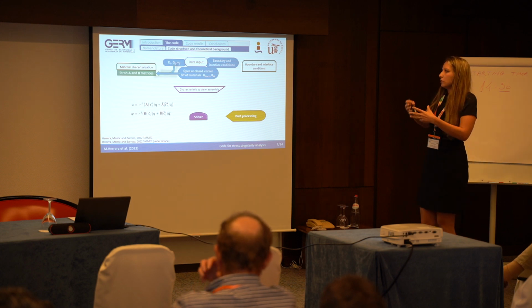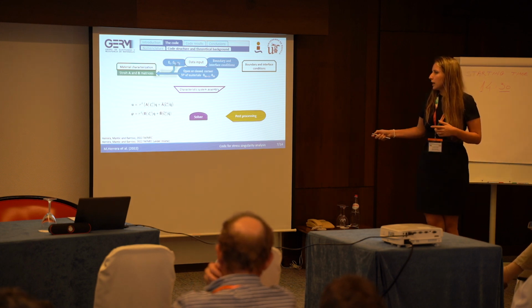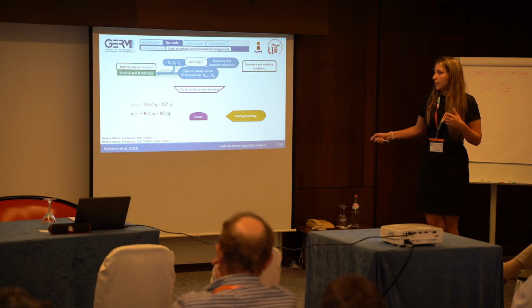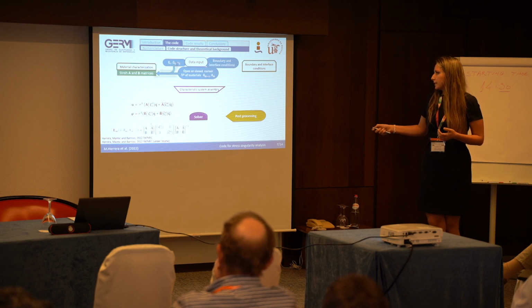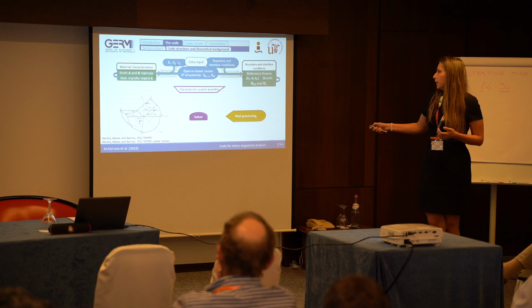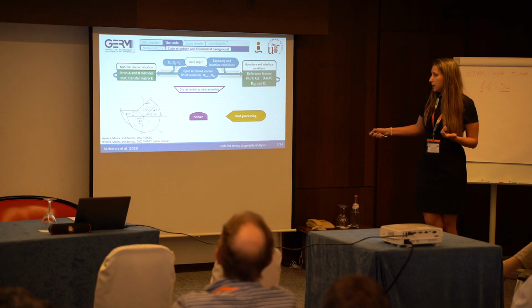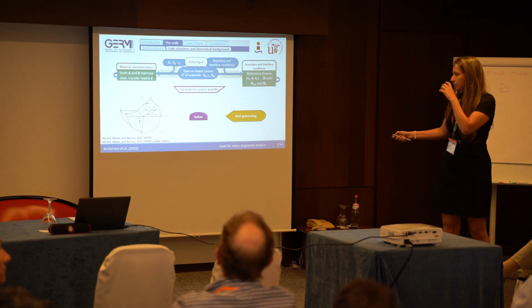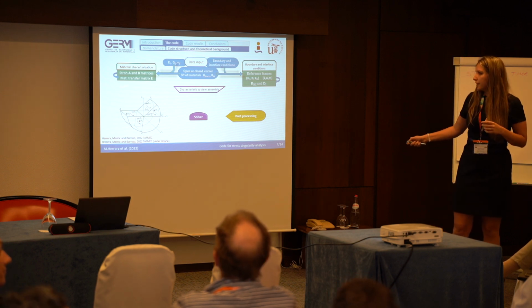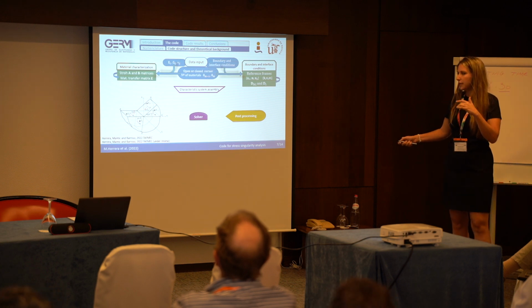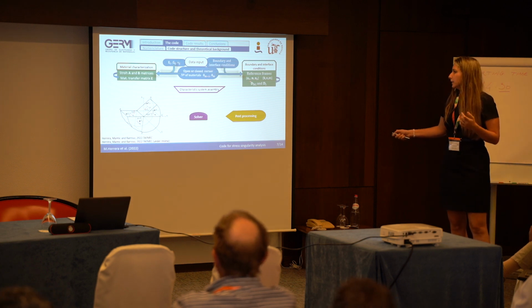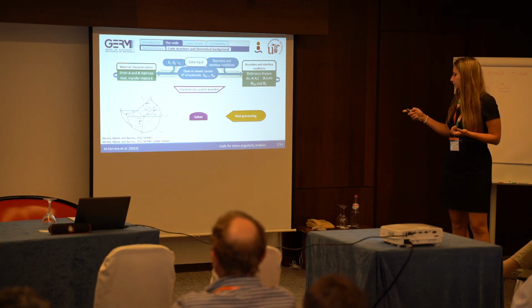When the code knows all the properties, it will calculate the Stroh matrices A and B for every material, and with them the transfer matrix E. With the boundary and interface conditions, the number of materials and the angles of the materials, it will calculate the reference frames for each material and for each wedge, and the boundary condition matrices and interface condition matrices.